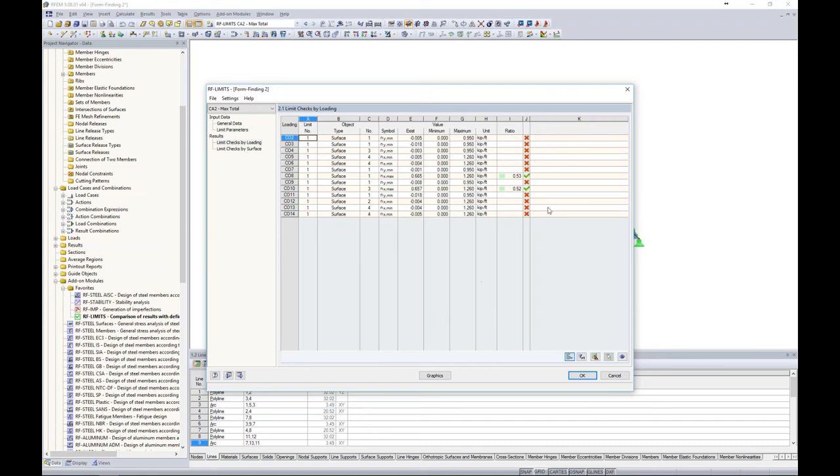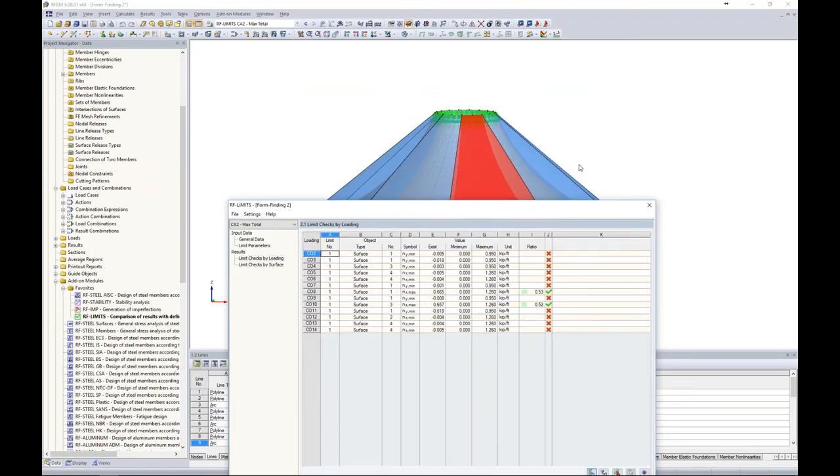Well, again, I'm seeing a lot of red here, which probably tells me there's some type of problem going on. But I look at my ratio, and I don't even have a ratio shown. Well, why is that? Looking at the existing forces, I have compression forces, and they're very, very small. So what exactly is going on here? Realistically, from the applied pre-stresses and my form finding, everything should be in tension, at least what I think.